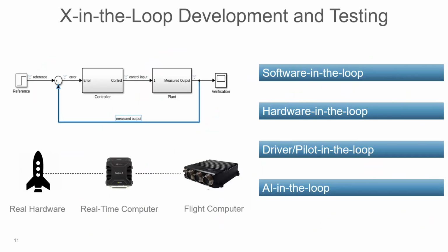This picture shows how engineers tie all this together from development to deployment. Initially, they start with software models of everything and they run simulations. As they gain confidence in the real-time simulation space, they start adding hardware pieces into the loop for testing until everything is replaced with real hardware and real controllers.